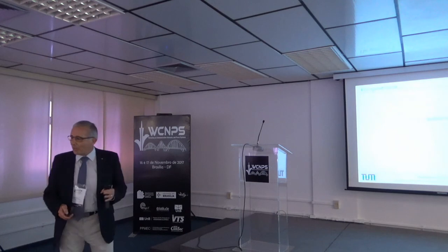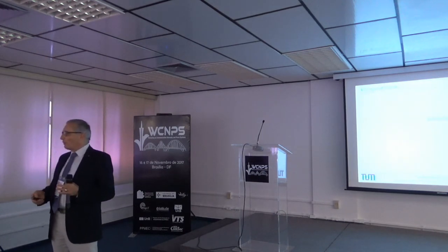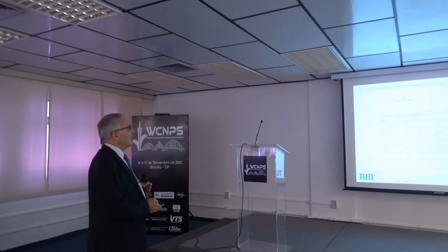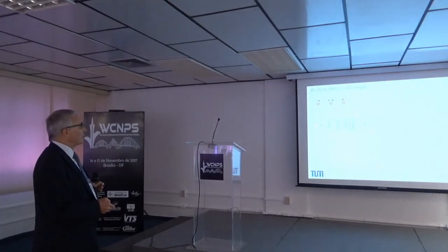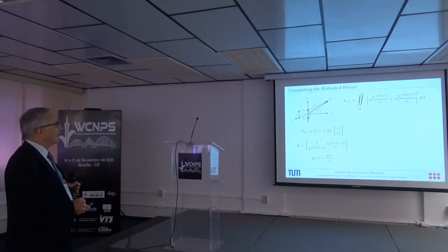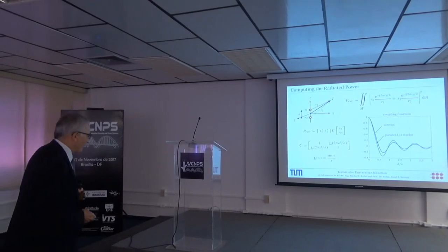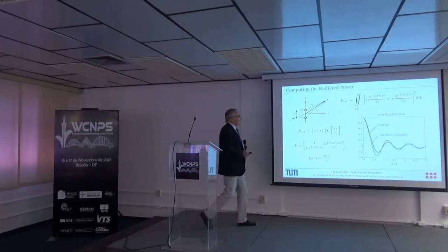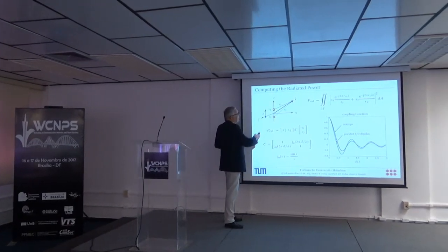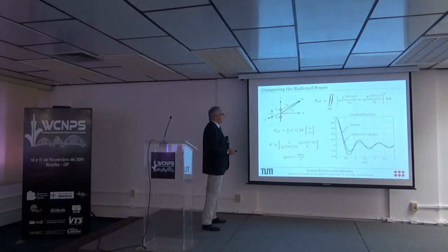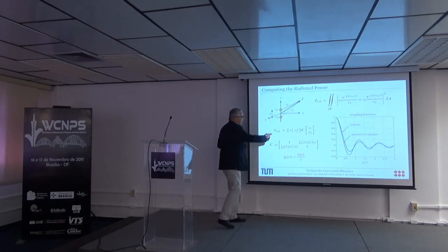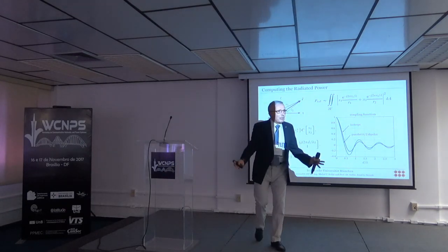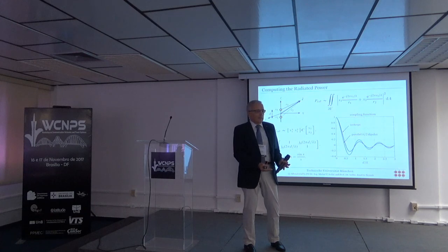Here, now I have to skip a number of slides from that tutorial because that would be too long, too many details. Let me quickly go through the important result which I will show you. This is one thing which is important, and what we see here is the following. Only for two antennas, with the axes being the currents which I send into these antennas, we can compute the radiated power by taking an integral over a sphere which encircles that antenna arrangement.